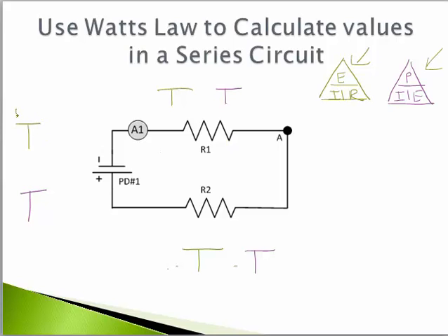So this is our Ohm's law. I'm going to say we have 120 volt source. And over here I have 10 ohms in this circuit and 20 ohms this resistor. From that, I can use my series circuit laws, and I know that R total in a circuit will equal R1 plus R2 in this case, so 10 plus 20 will give me 30 ohms total.